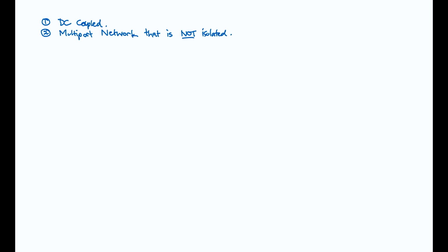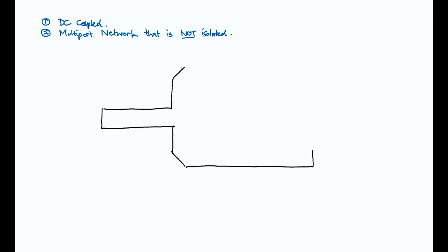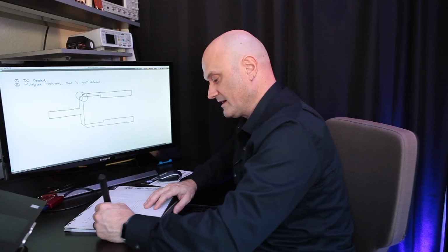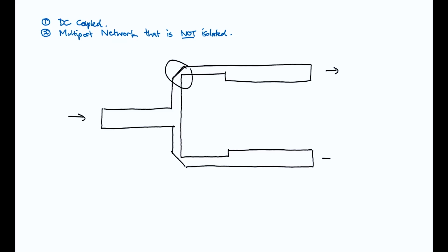That means if you get signals coming in, let's draw this again real quick, and I'm going to draw it slightly differently this time. Here's a typical power divider, with 100 ohm quarter wave segments here. This is just one way of doing it. They don't have to be cornered like this. It's just how I would do it, because typically I'd want a connection coming in here and connections carrying on out in the same direction. So it's not isolated. So here's the problem. Here's port 2, here's port 3, here's port 1. And presumably we have a source from port 1.